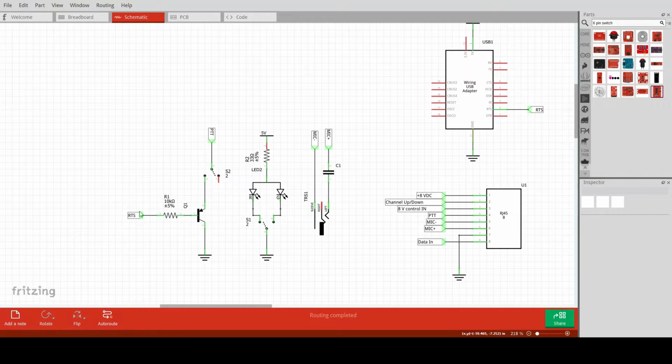So I just chose a 3906 and put it in with some type of resistor to make sure not too much current went into the base, and set that up on a breadboard.